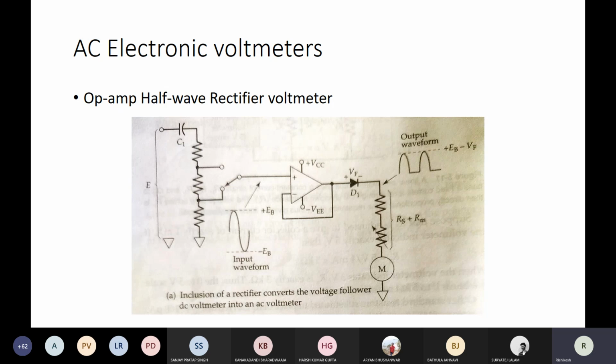The similar approach is taken here, except that we are utilizing the op-amp in association with PMMC. So the AC is not directly supplied to the PMMC, but is first operated on by the op-amp and then supplied. Here you can see that these different resistances RA, RB and RC are provided to choose the range for E.